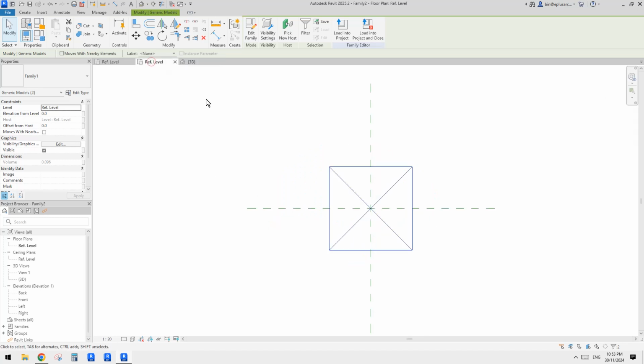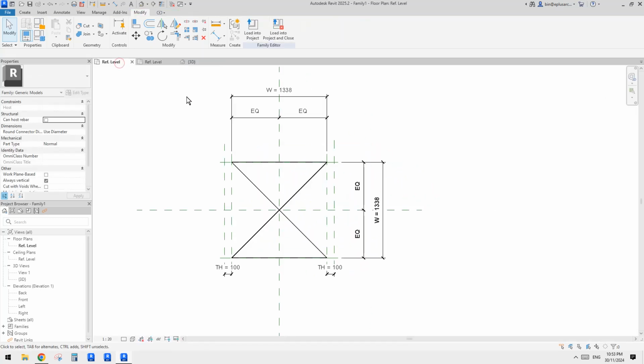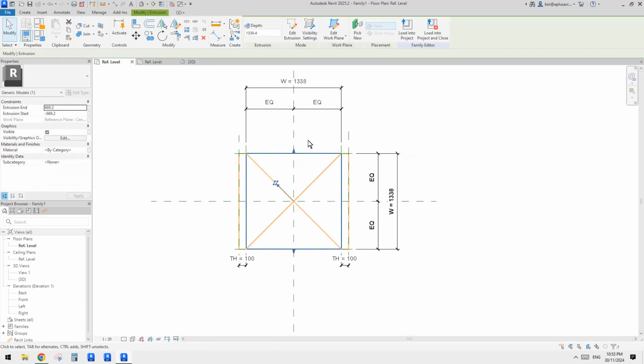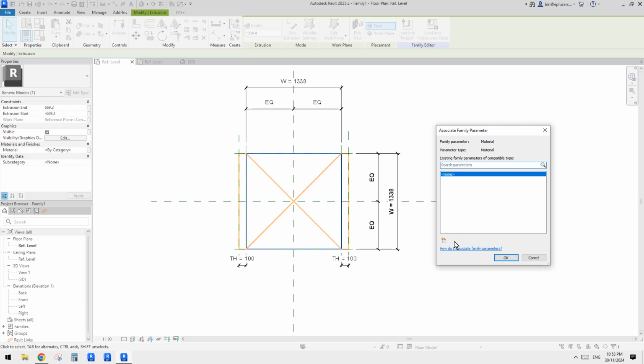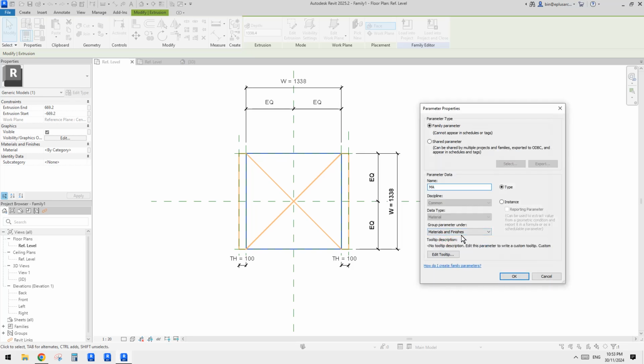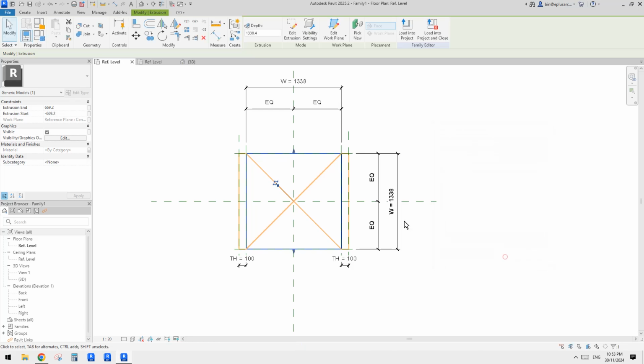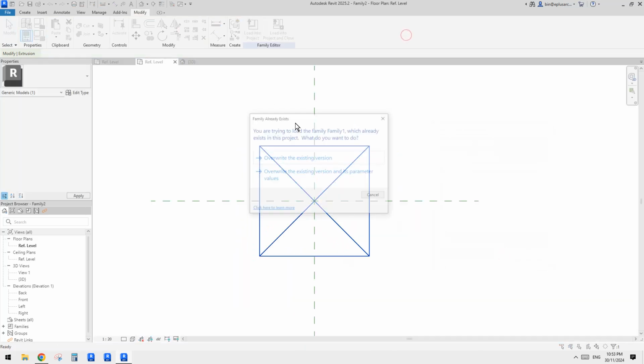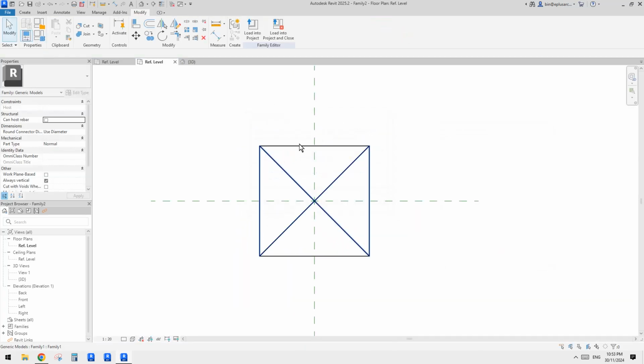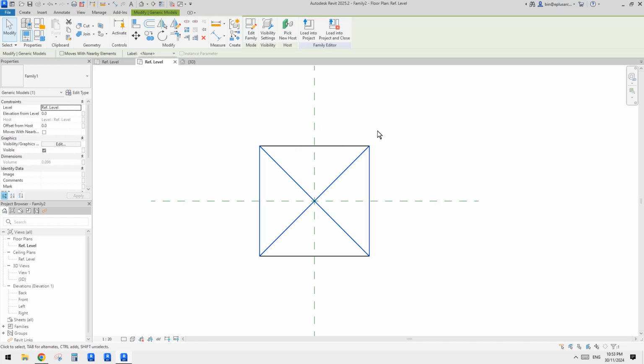And also on material. So yeah, in case you need to change the material, we need to go back here because we didn't have this material parameter. So we need to create a material. Okay. Right. So load this one back, override, select both, and edit type.